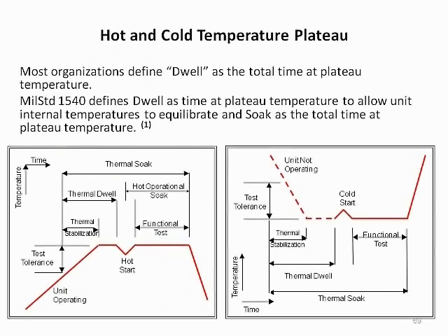When at a plateau, most organizations define dwell as the total time spent at the plateau temperature. MIL Standard 1540, however, defines dwell as just the time at the plateau temperature allocated to allow the unit internal temperatures to stabilize. MIL Standard 1540 calls the total time at the plateau temperature the soak period. It's important to bear this distinction in mind when working on DoD programs.